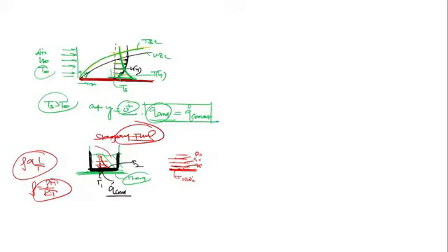So the fluid layer which is just on the surface will be at higher temperature, then its density will be lowest, and the fluid at this layer will have comparatively low temperature, then its density will be higher. Then the higher density fluid will try to come down and the lower density fluid will try to rise, because a buoyancy force will develop here. Yes or no? I told you in fluid mechanics, due to variation in density there is a buoyancy force, and that's called convection current, and this is called free convection or natural convection.